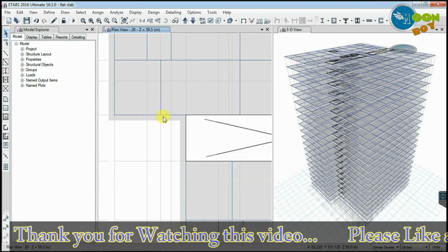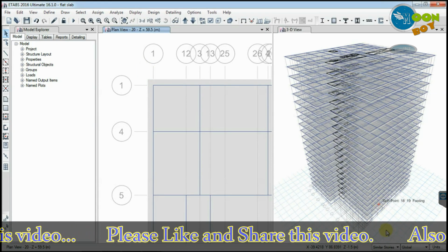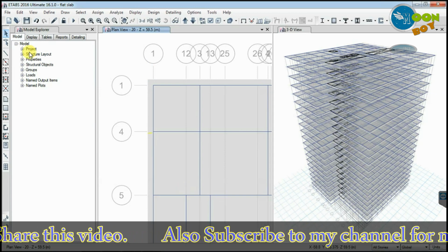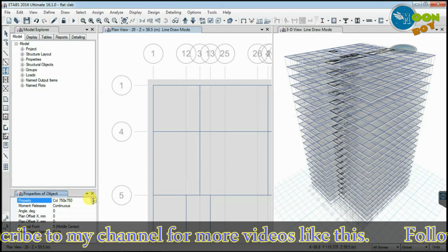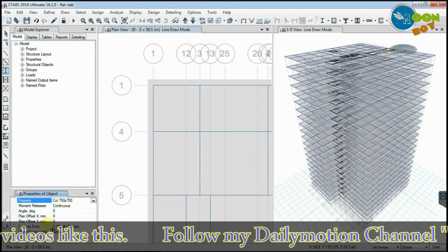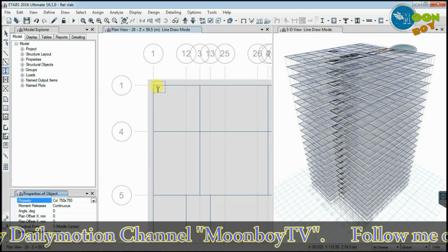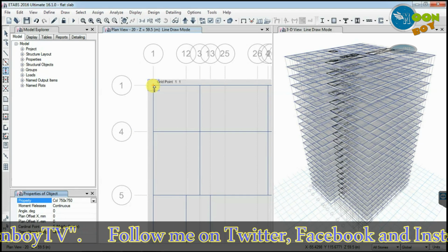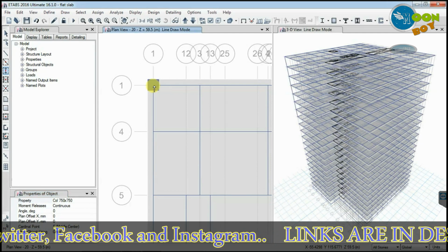Okay. Now from this corner we will start drawing the outside columns. For drawing the columns we will select here all stories. Then we'll select the quick draw column, and 750 by 750 column here, it is continuous, and we are holding the middle center, meaning we are holding the center point like this. Okay, so start clicking one by one like this.